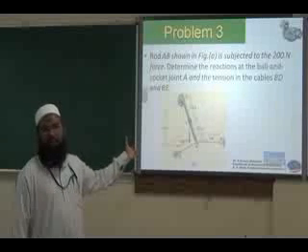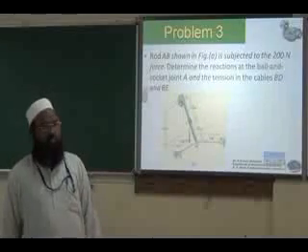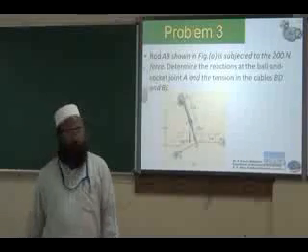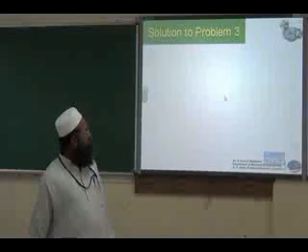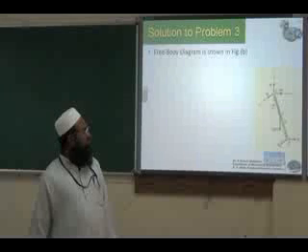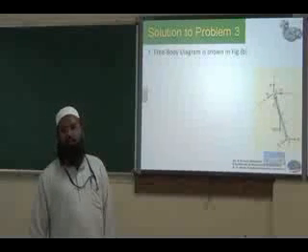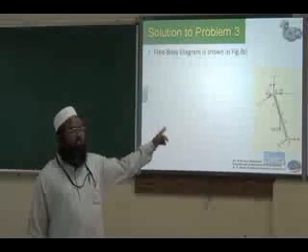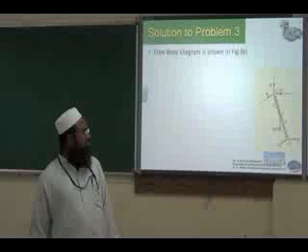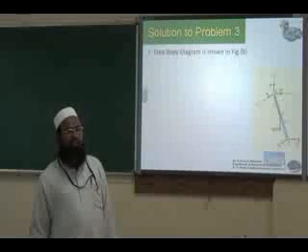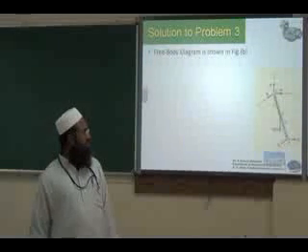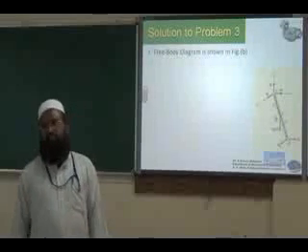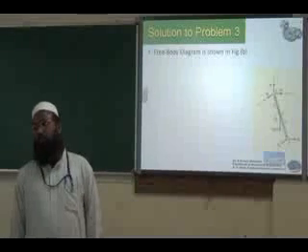Parallel to the Y and X axis respectively, two tensions. And also there is a middle applied force. So if you draw the free body diagram, the first step, this is the free body diagram. You have 3 reactions at point A due to the ball and socket joint. Then 2 tensions, the tension in cables BD and BE, denoted as TD and TE. Then you have an applied load at point C. So these are the force system you have.